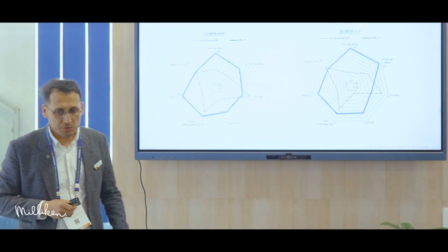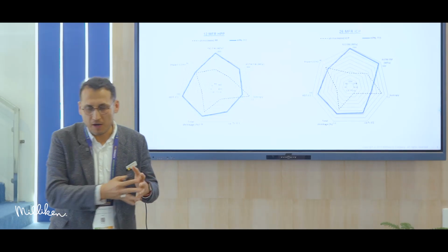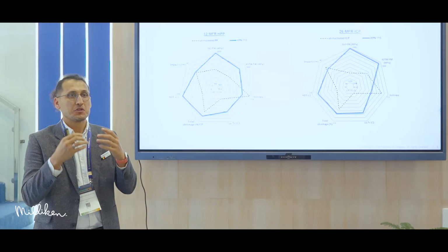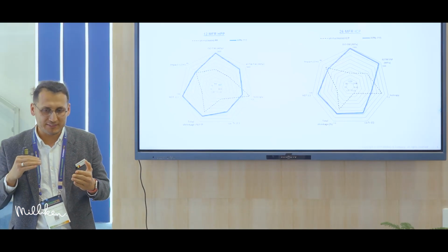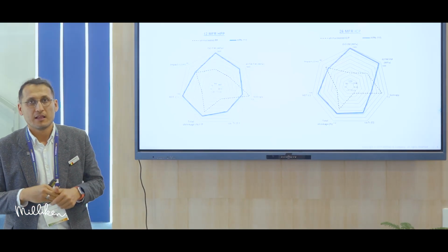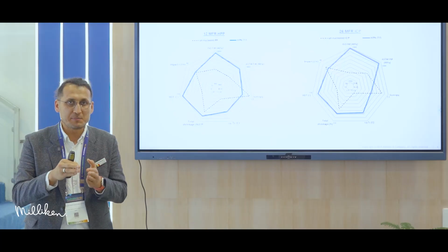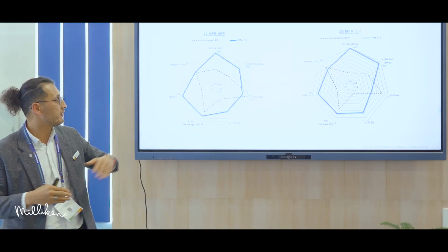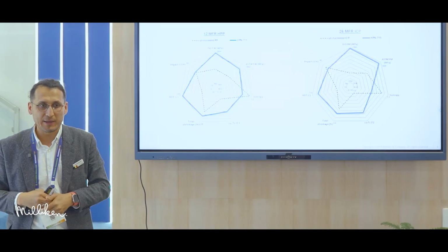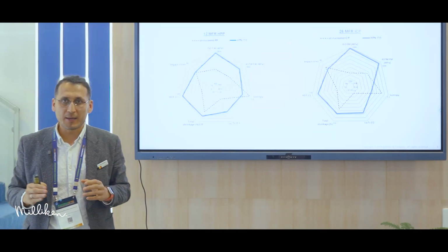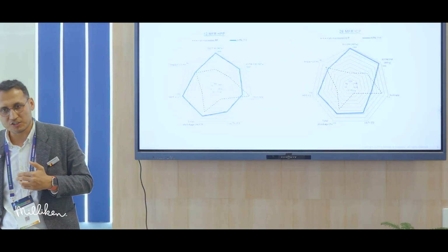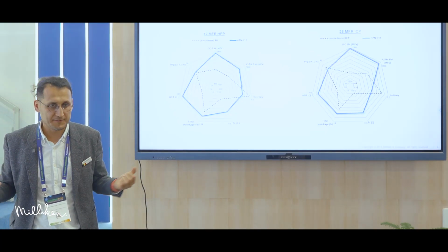And for nucleators, there are a bunch of different technologies. Within the different nucleators, because it's all impacting the crystal growth, right? Influencing the crystal growth to have a balanced performance of all these parameters is a balancing act. So sometimes you have a very strong stiffness, but on the contrary, you will lose impact.